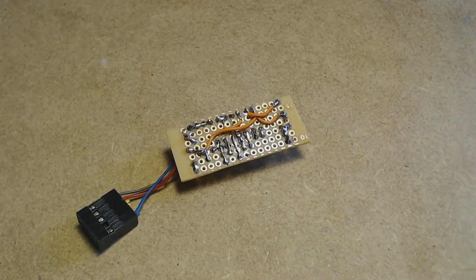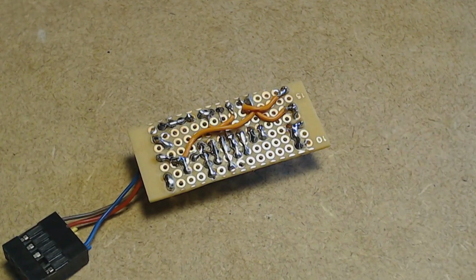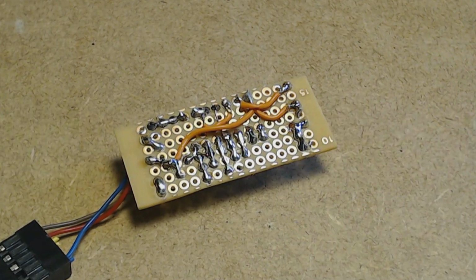I did many of the short and straight connections on the solder side using folded down component leads instead of separate wires. This makes for quick progress, as long as you're aware that you're never going to be able to desolder any of these later.